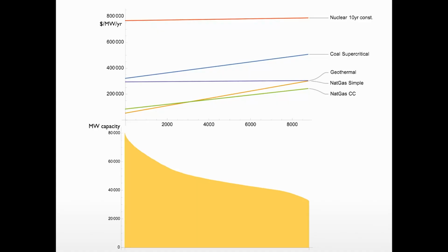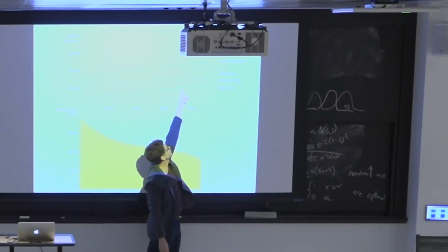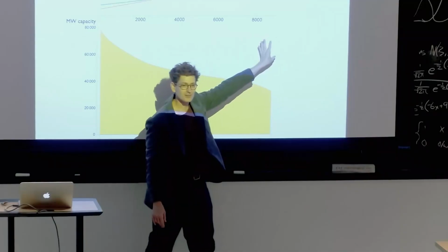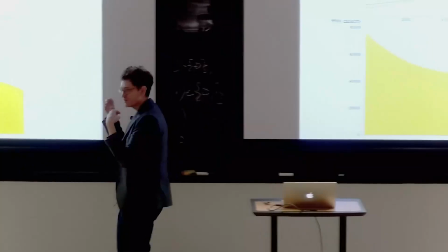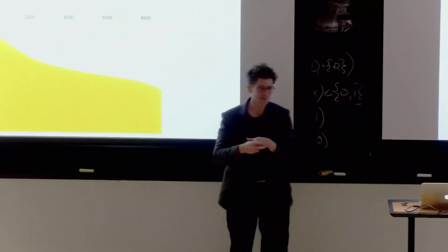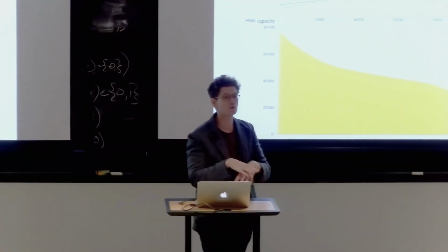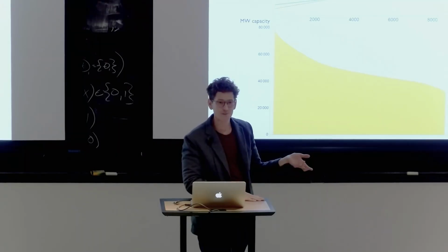It operates similarly to geothermal. So if we could bring the cost of nuclear down, the capital cost, which is to bring down the intercept on this axis, at some point it would come across and it would pop out underneath the green line here. And then it would be the baseload technology. So that's what baseload means. Its best hope of financial success is to be operated as a baseload generator. But there's no requirement that baseload must be serviced by something like nuclear. It can be serviced by solar. You just have to have the reliability to be on all the time.